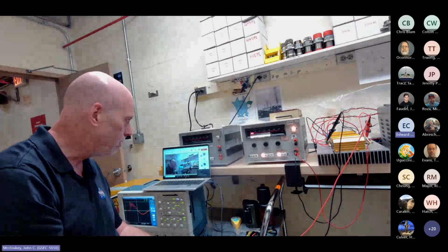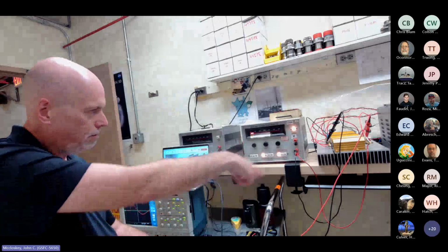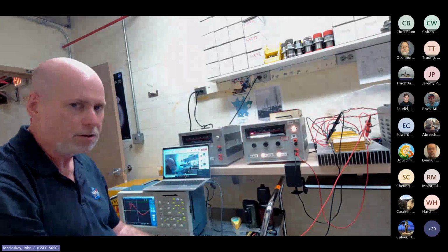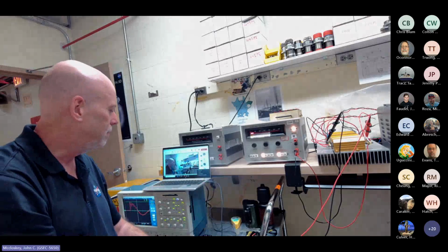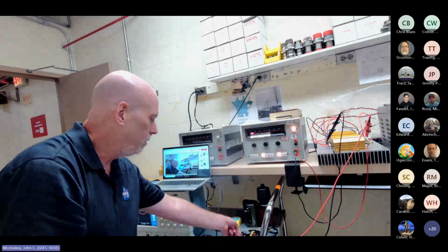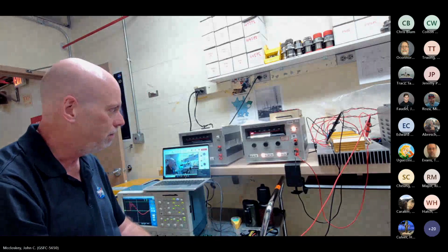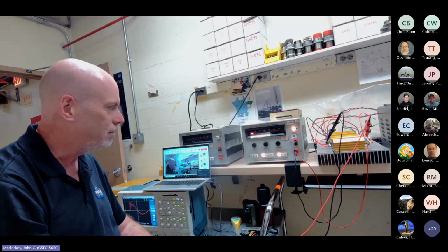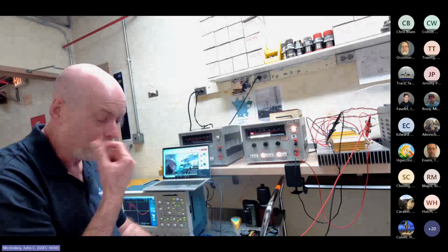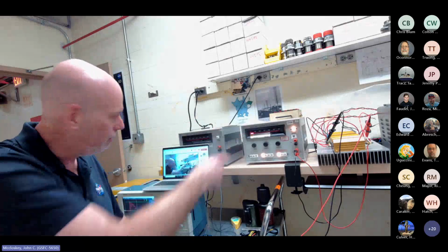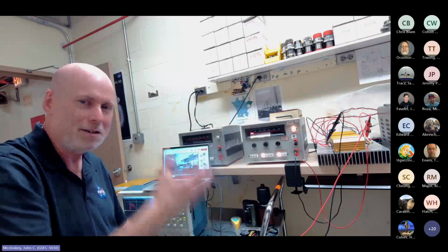So agreed. The unit is generating some ringing on its own, and it's just made worse when you hang a meter of uncontrolled transmission line over to possibly a wire wound resistor. But yeah, all these things to pay attention to when you're in the lab and you're seeing some strange things. As we say at EMC, it's all the hidden schematic, right? You think that 5 ohm resistor is just, you draw your little resistor symbol and put 5 ohms on it and you call it a day.